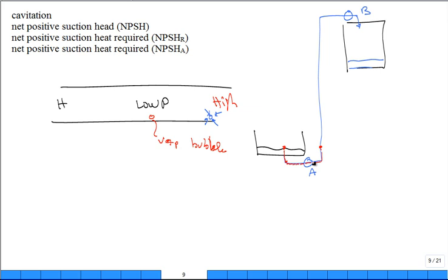And you know you're going to have head loss, so you know at this point right here it's below atmospheric pressure. And as you keep going up, guess what? More and more and more below atmospheric pressure. It could get so far below atmospheric pressure that it gets down in the range of the vapor pressure of the water that you're trying to pull up, and you get vapor.